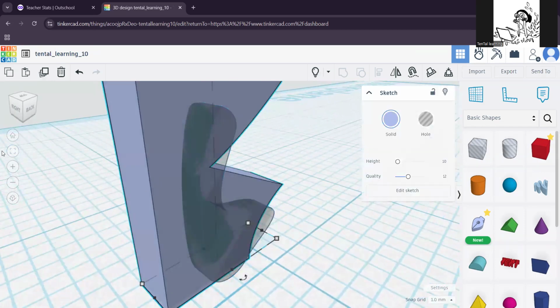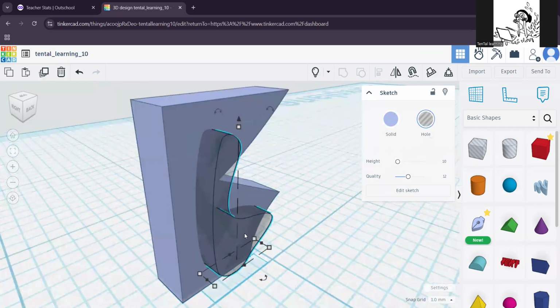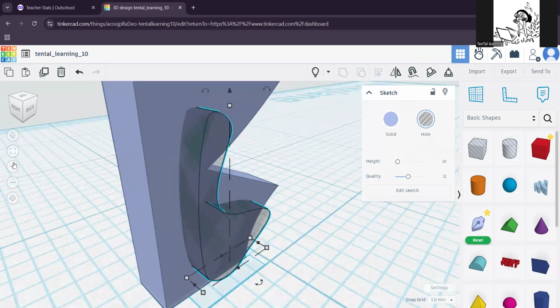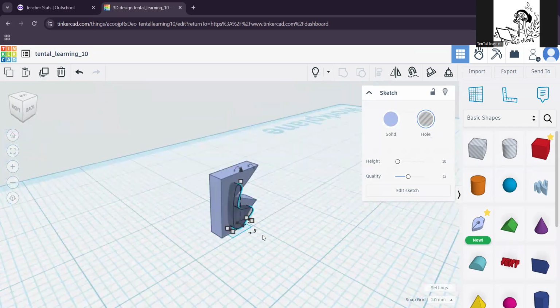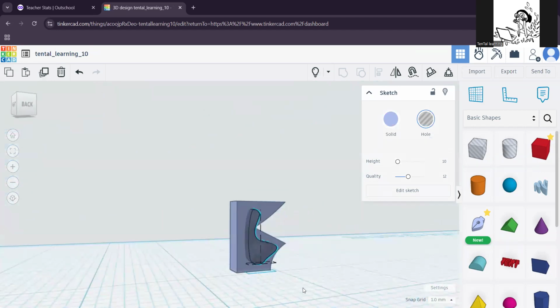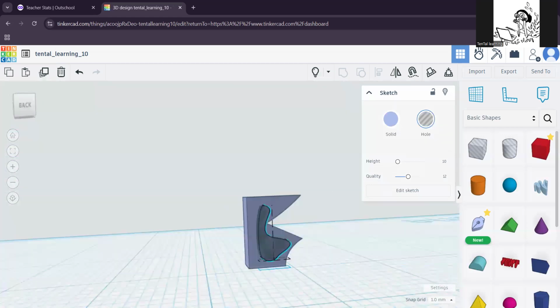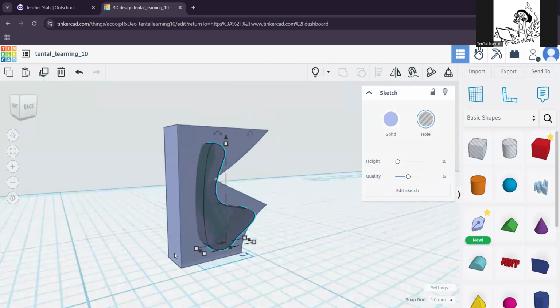When you select something, you click this, or also it has a shortcut F on keyboard. So whatever you select, you can press F on your keyboard, or also this one does the same thing. You can just see that object better. And to rotate, use your right mouse button and you can see the object like that.